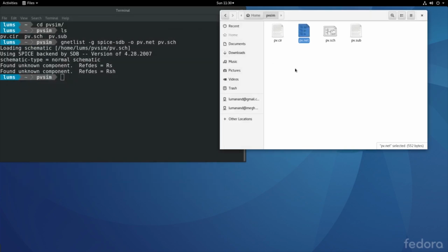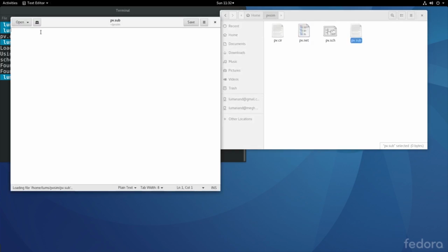I'll close this and open pv.sub. So that is open. The first line is normally a comment line, but you can put in some comments. So let me type in something meaningful, library of component models. Then it is better that you have some demarcation. Star would indicate comments. So let's say class of diodes, again with a star, all these are comment lines.